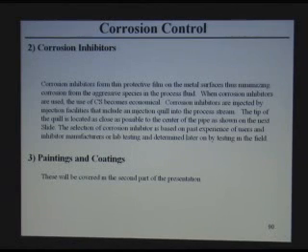You can use carbon steel when you use corrosion inhibitors, of course, if it is proven to be successful. It is used extensively, like in North Slope in CO2 corrosion prevention. It is injected with produced water. It is injected with the crude itself, so it gives protection. And in such cases, you can use carbon steel.